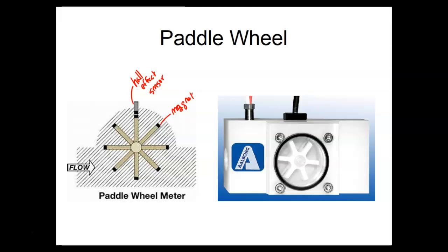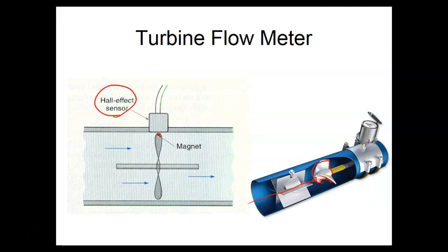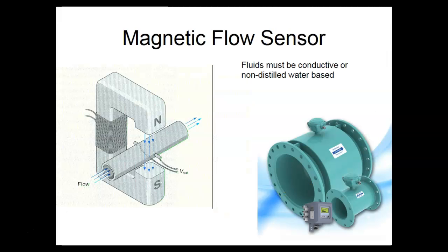The programmable logic controller takes this input, we bring it into a counter over time, figure the math formula, and work out the flow rate from this. And this is digital too.